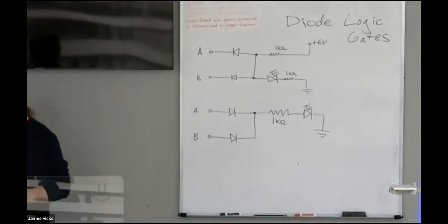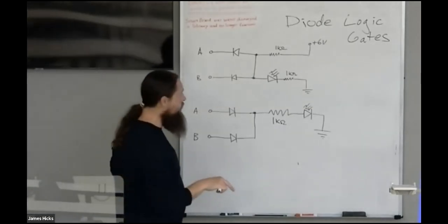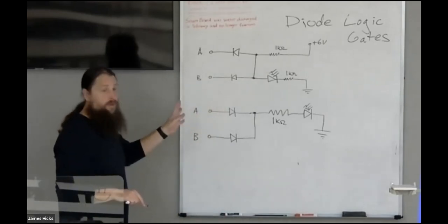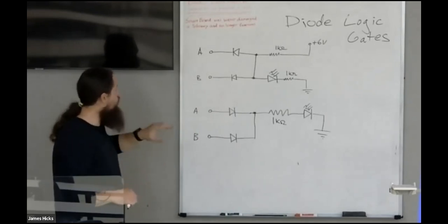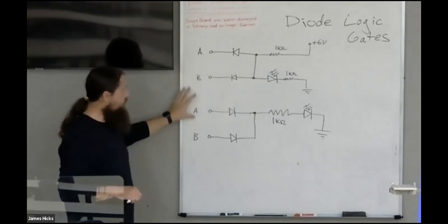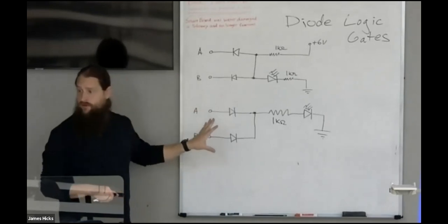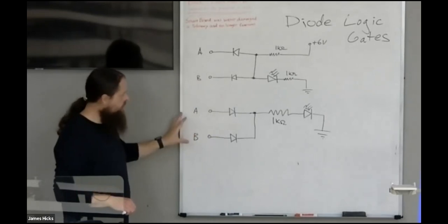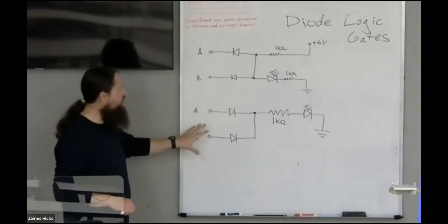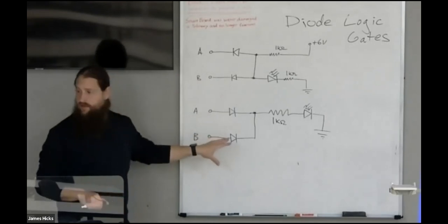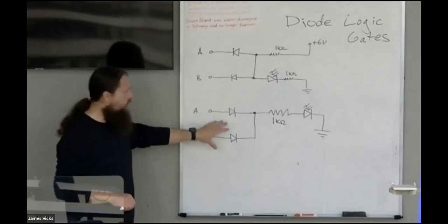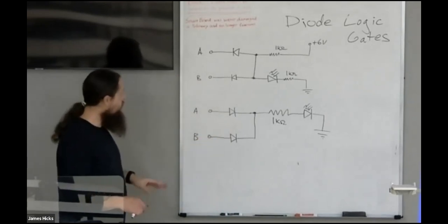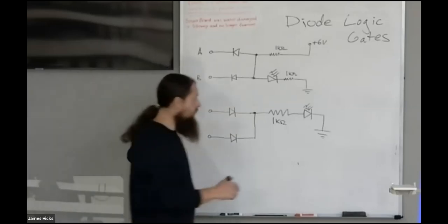I'm going to do a little bit real quick with some diode logic gates and then talk more about the flip-flop logic gates. So there's two different logic gates here. They're just diodes and no transistors, so these are a little bit simpler. If you need a logic gate real quick, the problem with doing diode-based logic gates is that the diodes don't typically switch as fast. So anyway, let's start with the bottom one.